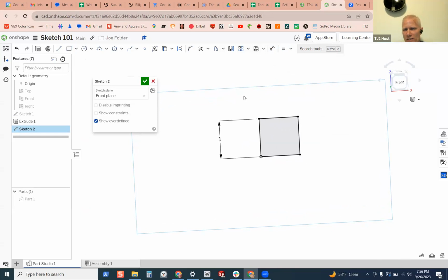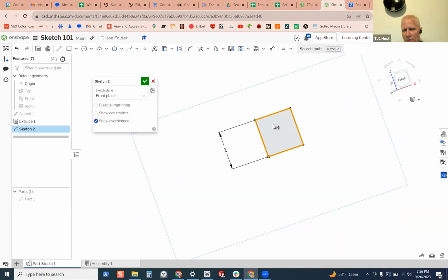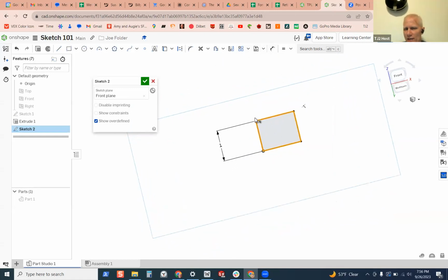When you're selecting parts in a sketch, if I select from the top down this way, it only selects parts that are all the way in. You see, it only selected these two because those were all the way in. On the other hand, if I select from this way down, as long as I'm touching, you're in. So here, I'm not selecting those two, but you see, it still got it. So it's anything touching. This is a very powerful tool that you can use a lot.